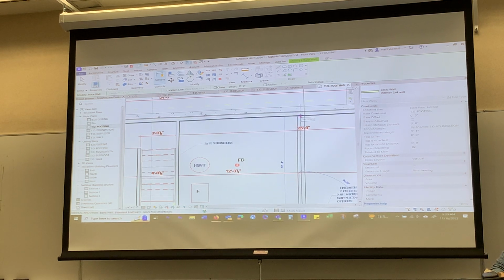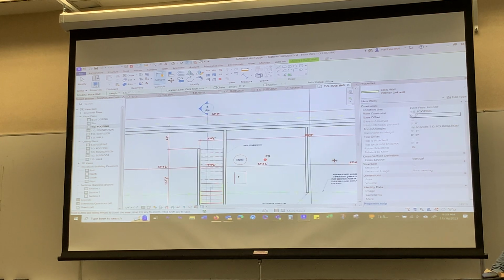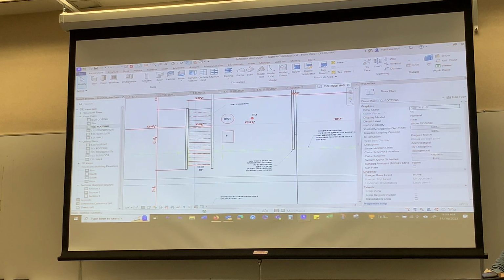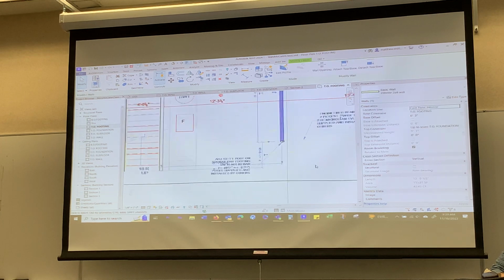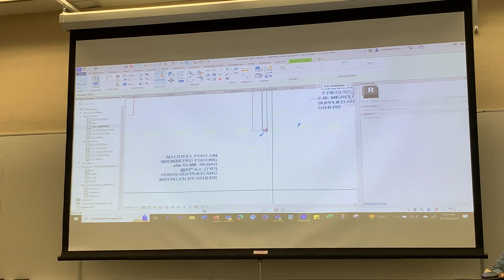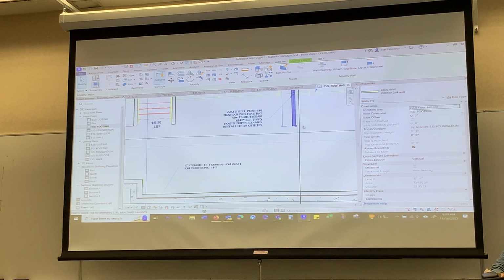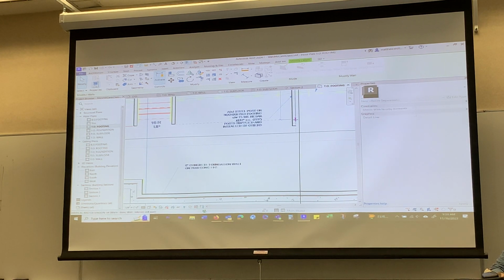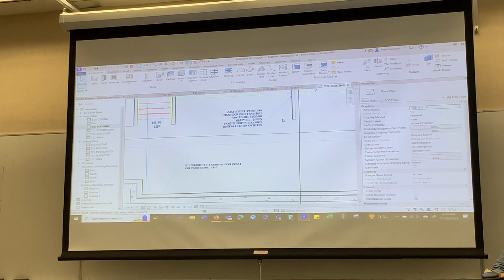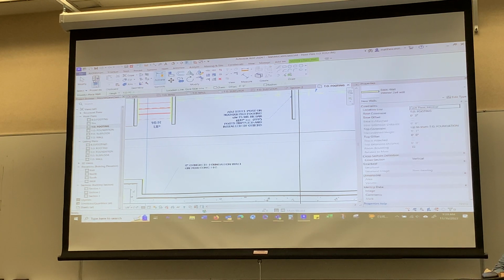And just come in at 90 degrees and bang it to the wall. Let go, highlight the wall, and then drag my wall down. And then, so I can see the other wall, I'll get one of those little cheater lines. There it is. Good, awesome. You don't have to do this now. I'm just doing it to show you what you need to do. I think it comes up later in the assignment. It talks about getting you to do it, and then you just close this in.